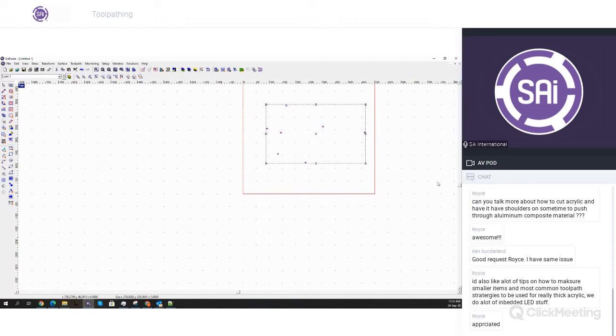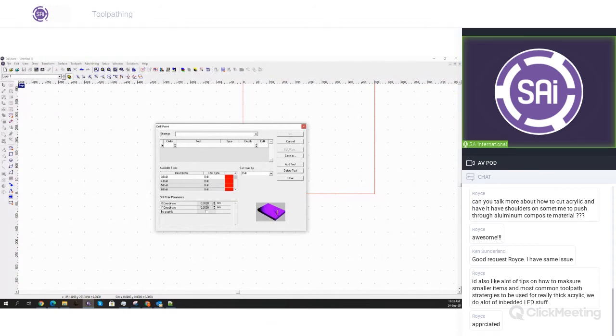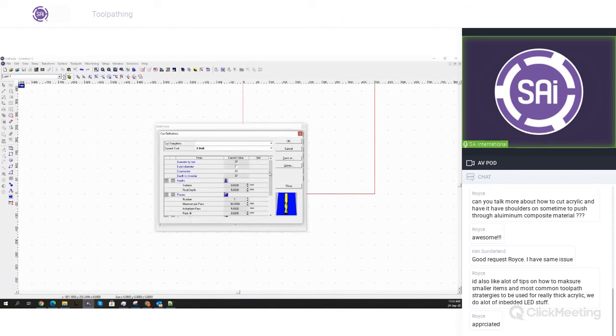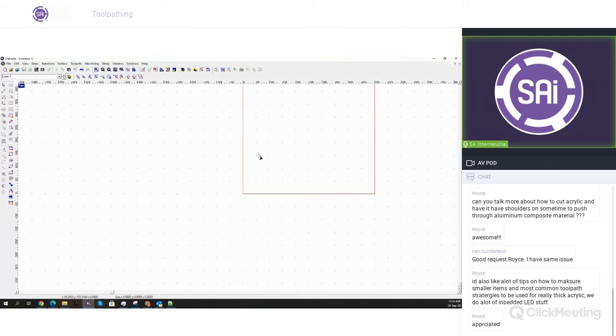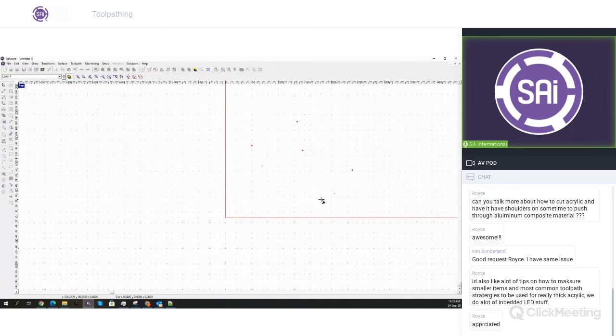For the drill array, a regular drilling point, you can just set up the coordinate for it, or you can do that by graphics. So here we can set a depth by graphic. Here, of course, we also have the possibility to set the feed rates, passes, and so on. In this case, I will just leave that unused. And now it will allow me to set up drill points everywhere I wish until I use my right mouse button.